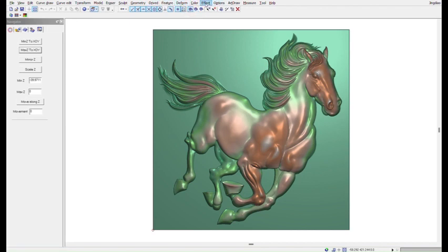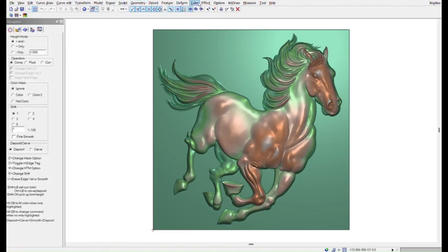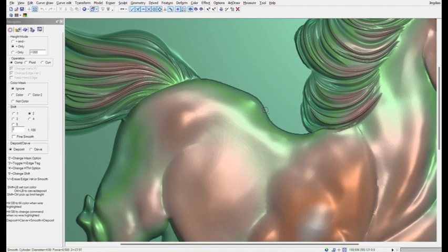In the smooth operation, you can use several tools, like effect smooth, and smooth whole, which you can use for one-time smoothing, and effect smooth, where you can select the path and smooth. Select it here, and plus only means it does not carve or dig into the model. So you have to select the size of the curve, and then you can zoom in and move along these edges.